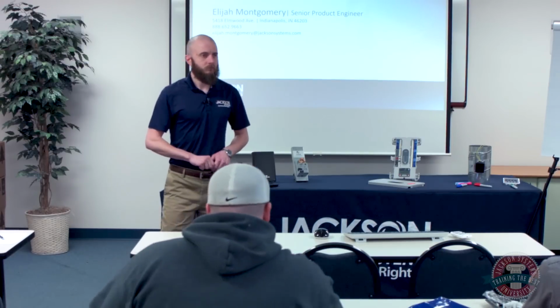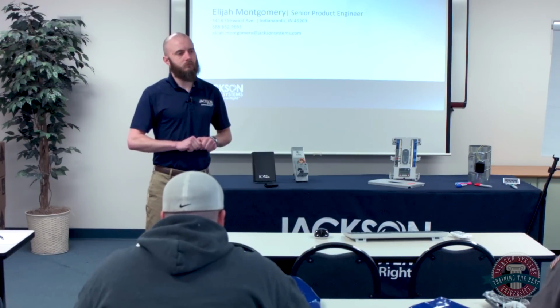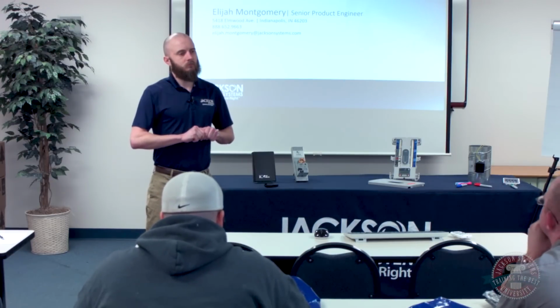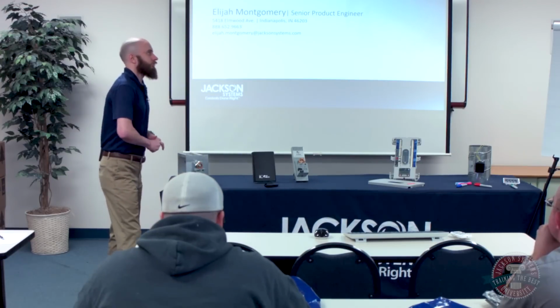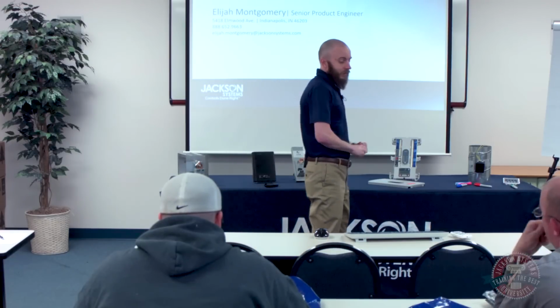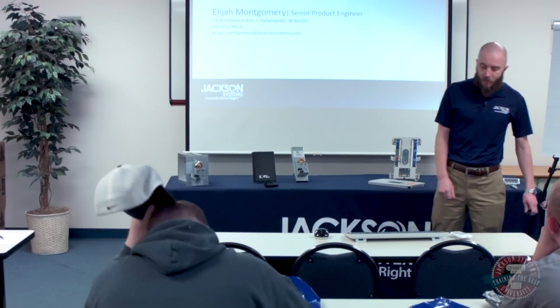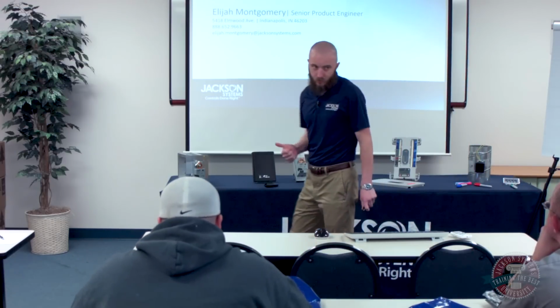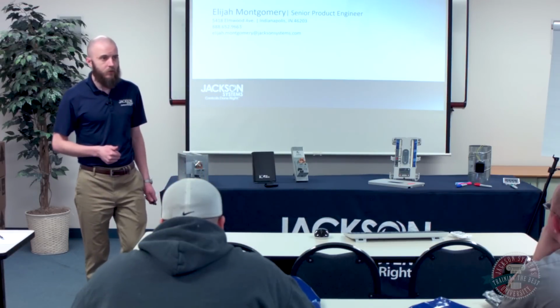Okay, so Frank asked if your transformer is too small for all zones, can you put another one in parallel to get more amps? I would not do that. So I wouldn't just parallel two transformers together. I would increase the size of your transformer first of all. So I'd replace it with a larger rated one.